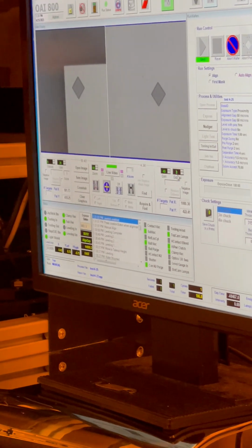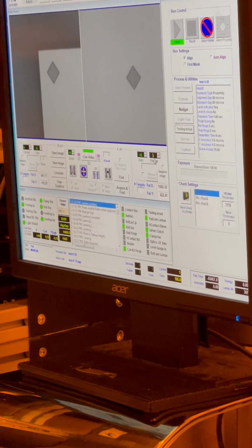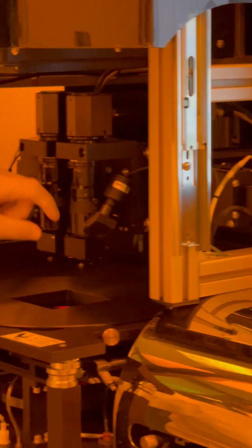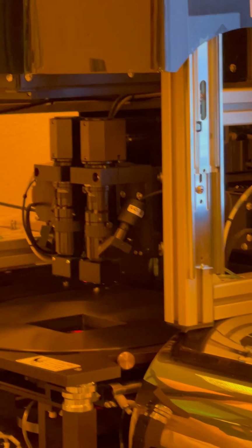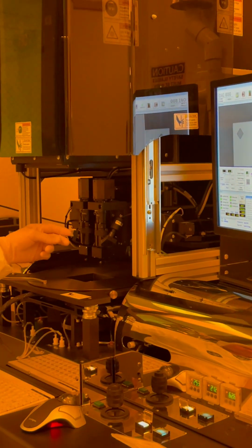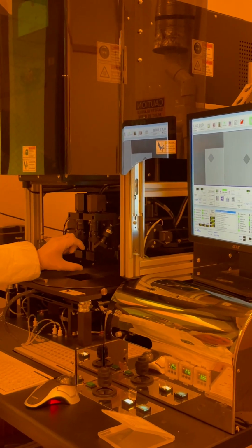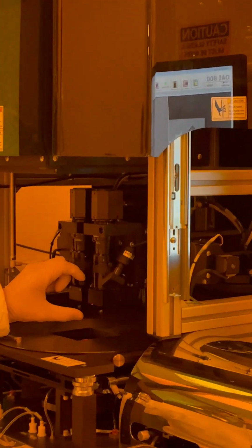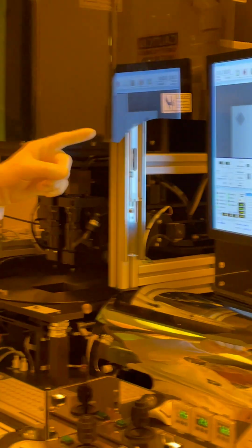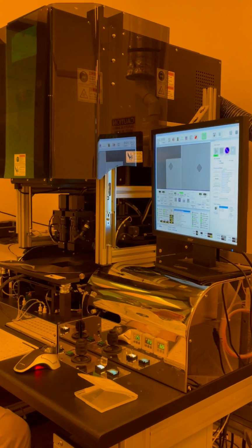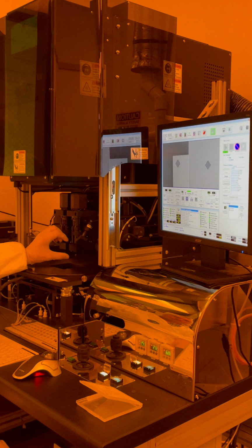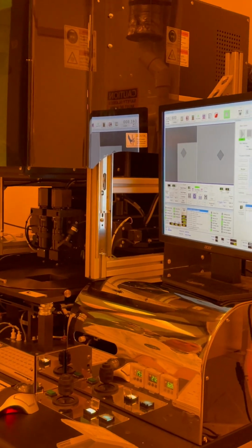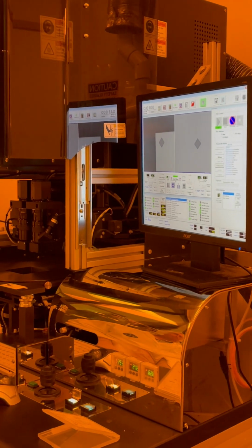These are long working distance optics with prism assemblies attached to the end, because they need to get really close together for small wafers. Normally, we have Mitutoyo infinity corrected objectives that are very high resolution. This would be crystal clear with a little bit better objective on it. But it's still pretty good.